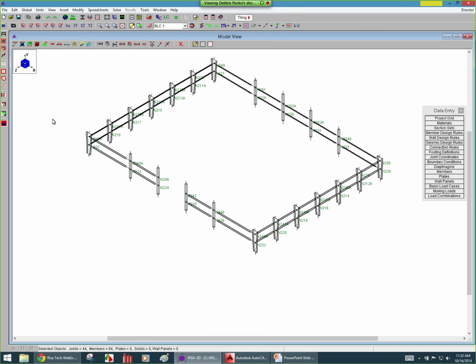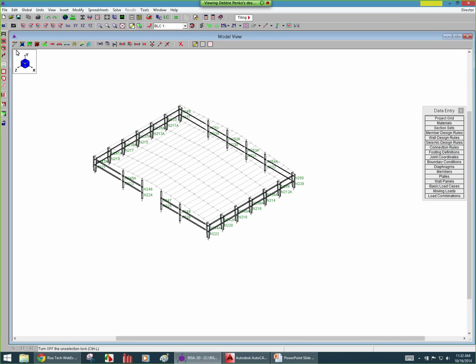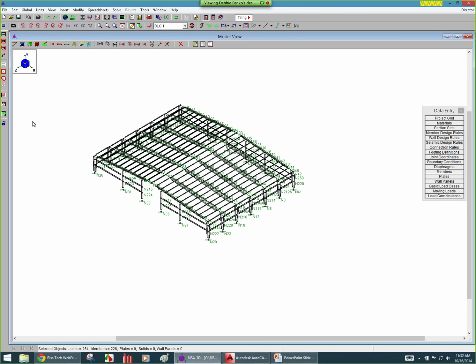It's up to you whether you do it one way versus the other. But again, if this is to help support the sheathing, maybe they would see the load, maybe they wouldn't, depending on how you're attaching that. So I'll see how the purlins are going to see the load of the area loads and the girts won't, and we'll see how that worked because it was based on the material type, or the member type, excuse me.